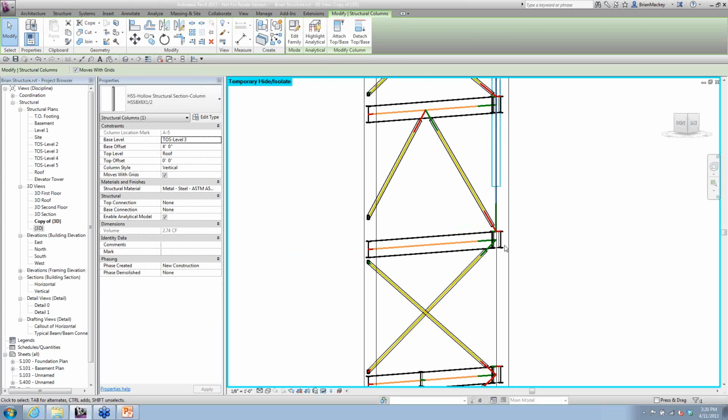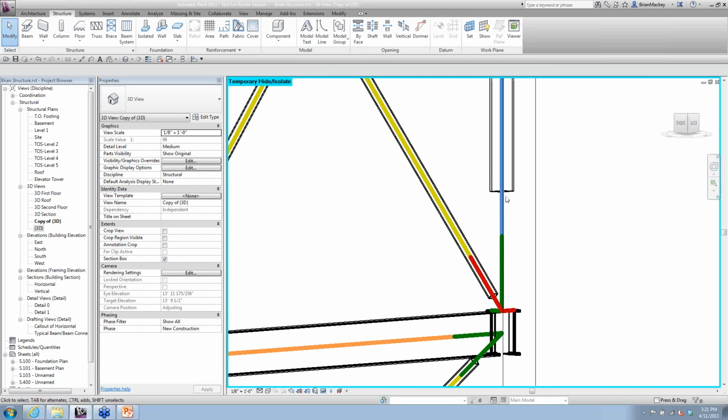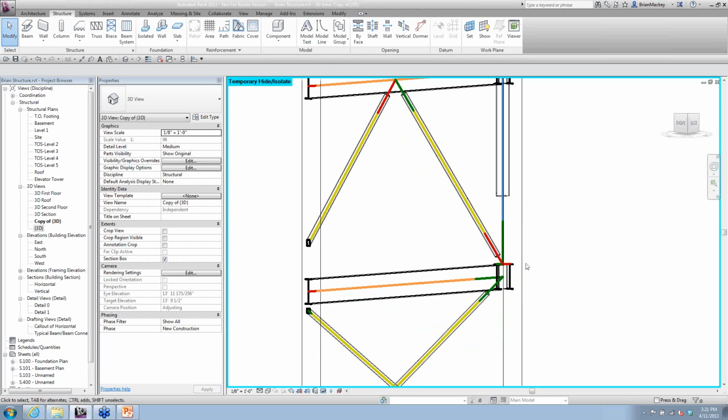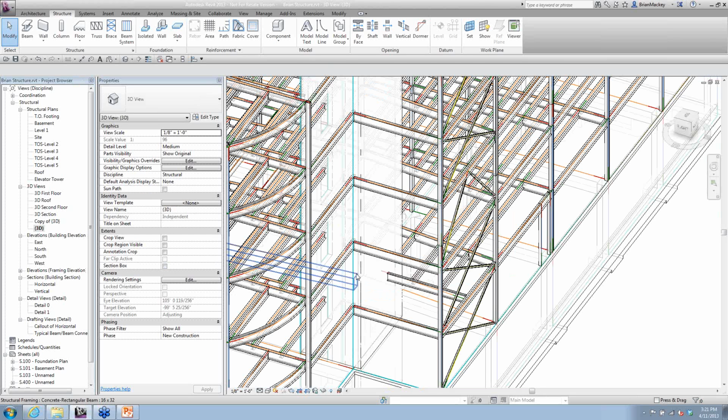So it's really about controlling, depending on the analytical program that you need, what we need to do for the analytical side of this. Am I doing top projection, bottom projection? Does the auto detect work for me or not? And we don't have to do those on a one-off basis. If I know that I need to take all of the base columns and do that, absolutely I can do that from a 3D view.